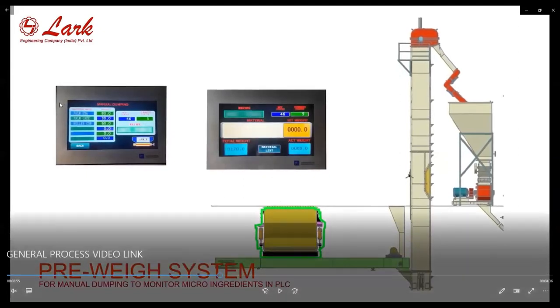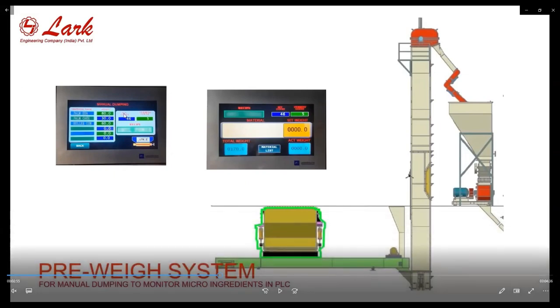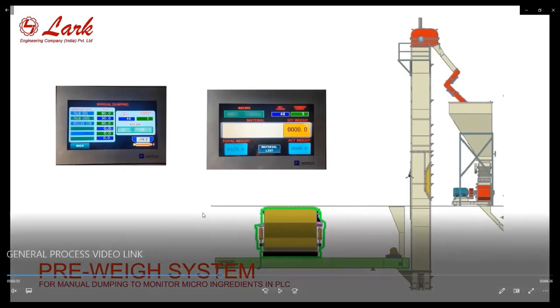This is a manual dumping screen. Here is the item name and the set weight. The name displays on the screen, and as per the sequence of this PLC screen, the operator putting the material manually into the grinder elevator has to maintain the sequence. Everything can be recorded, for example if instead of 80 kg he puts 82 or 84. So that can be monitored and controlled even in the manual process.